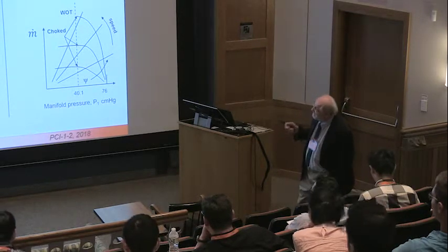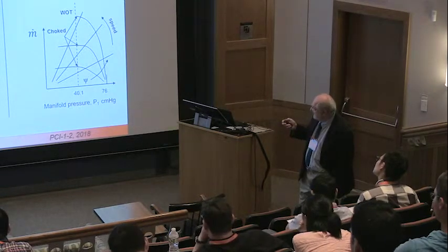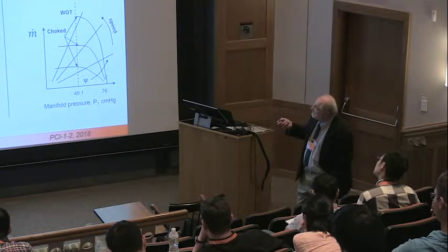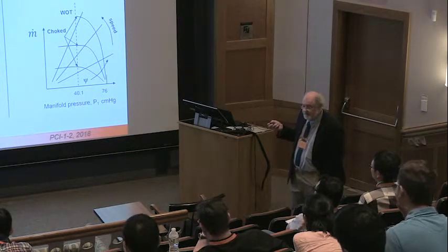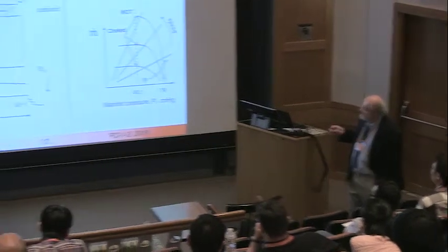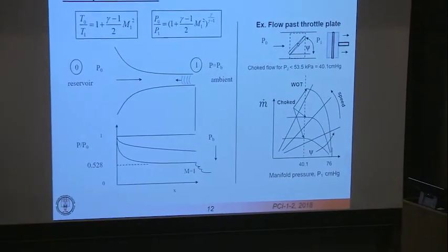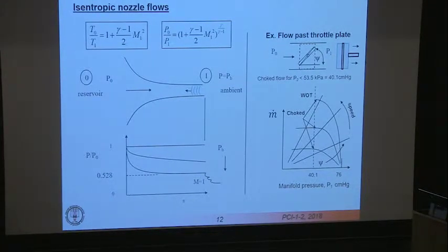If I look at the equations for isentropic flow, I can actually use them to study nozzles. My energy equation can be shown to give you this result here. And from the isentropic flow equations, I can relate that to pressure changes through the ratio of the specific heats. And so the equations are in the boxes. So let's just look at an example. I have a reservoir at P0, that's our stagnation state. And it's connected through a nozzle, a converging nozzle, to the ambient here, which is at a certain pressure.